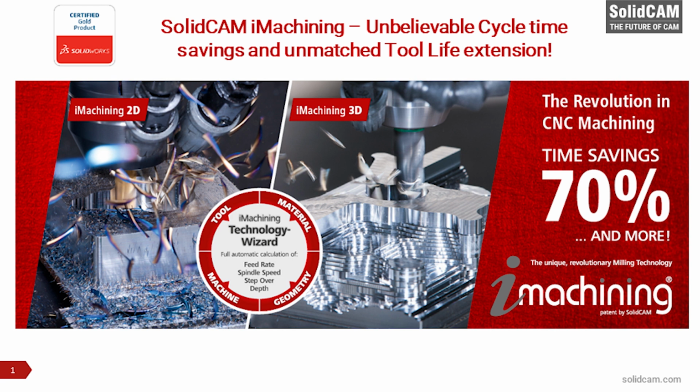I think that's where you're going to see it a lot, like for instance the titaniums and the Inconels. Those materials are really hard to get good performance out of a tool, and they're very, very damaging to the tool. With iMachining, one of the biggest things we see in those materials like titaniums and Inconels is that the tool life goes up more dramatically than it would, for instance, in an aluminum.